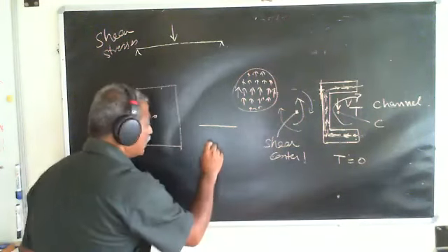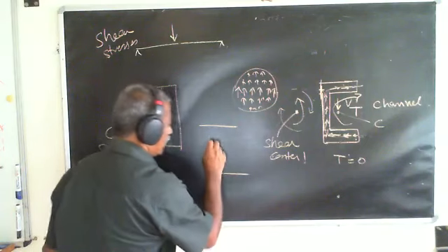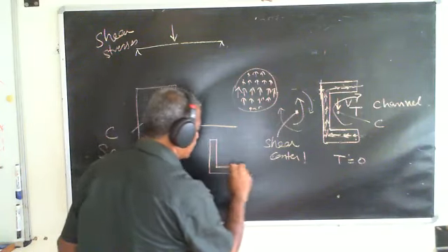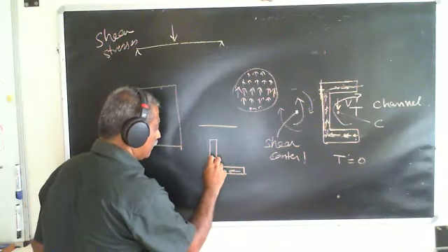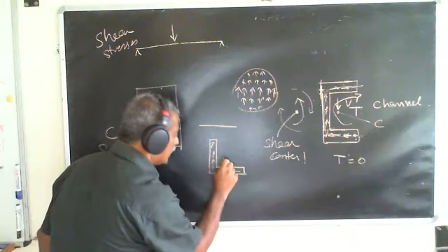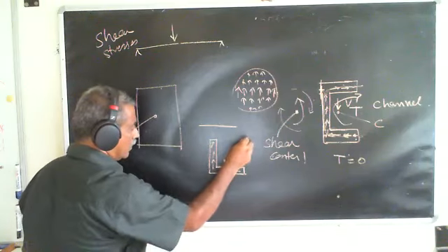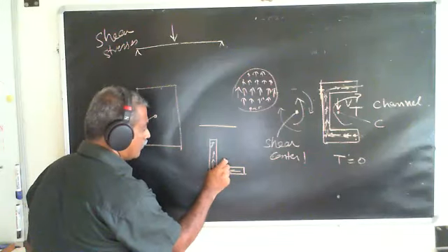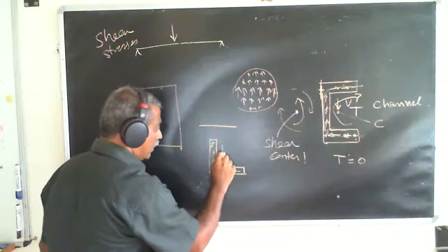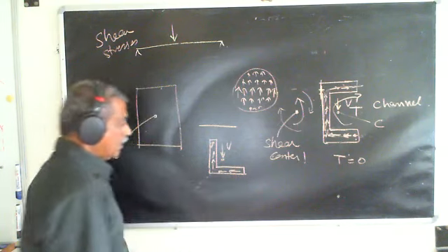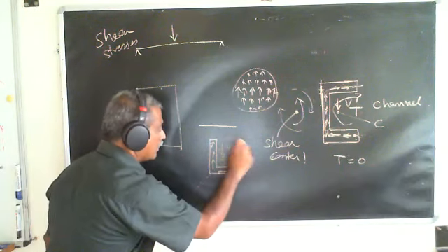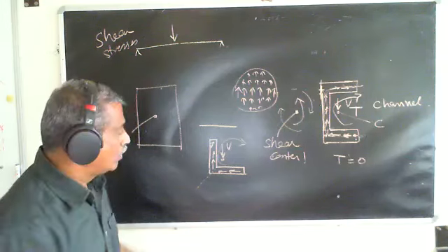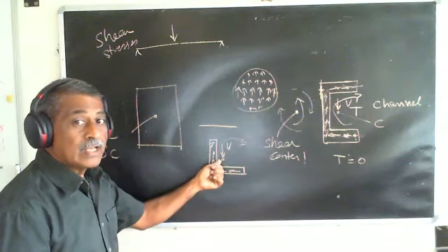How about an angular L cross section? Well, this is the shear flow, correct? Centroid is somewhere here, right? If I apply the shear in this direction, definitely there will be an unbalanced torque that is coming about, and it's not desirable to do that.